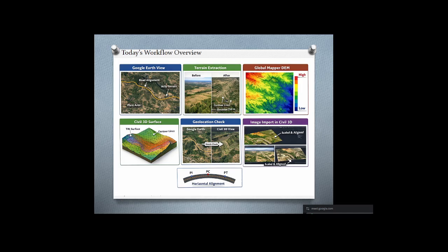The third thing is the Global Mapper DEM. We show elevation using colors. Here we indicate different types of colors in the third image. Red is for high elevation and blue is for lower elevation. You can set the colors as per your requirement. If you want blue as high, you can set that, which is not a big issue, but you have to understand what the colors are telling you. If the data is missing or unclear, we refine it here also.